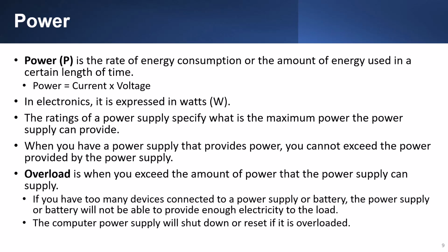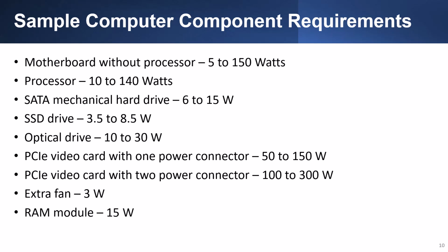If you have too many devices connected to the power supply or battery, the power supply or battery will not be able to provide enough electricity to the load. The computer power supply will shut down or reset if it is overloaded. When you figure out load, you will have to add all of the components' power consumptions to see if your power supply can provide enough power.